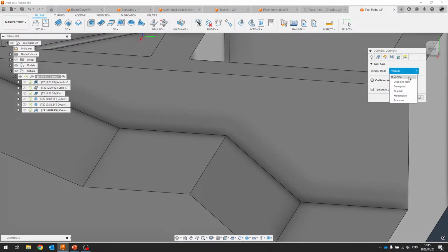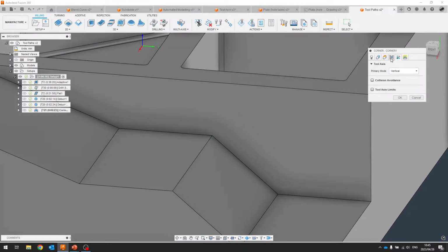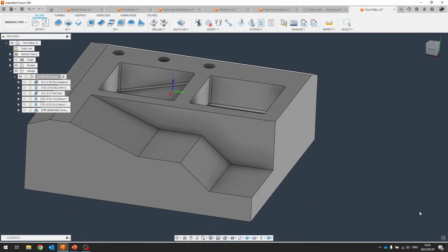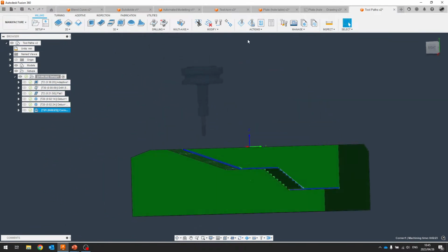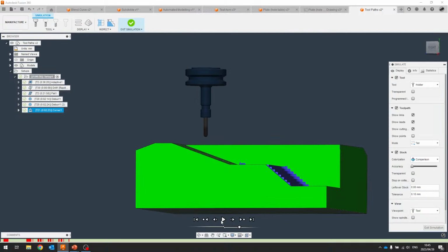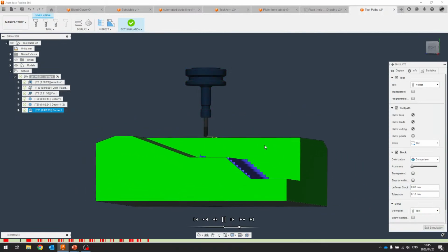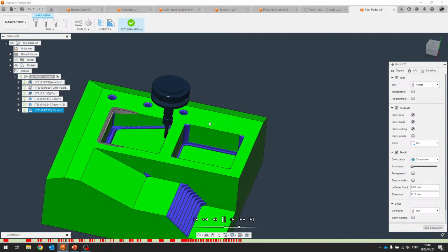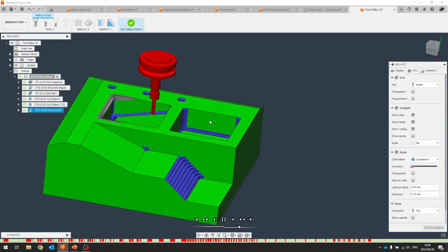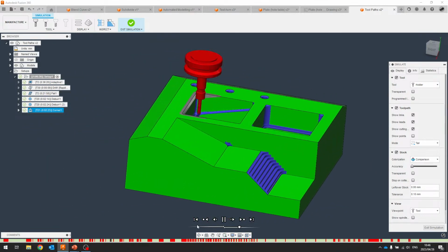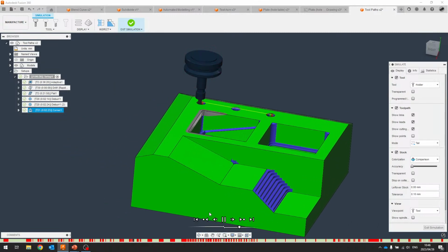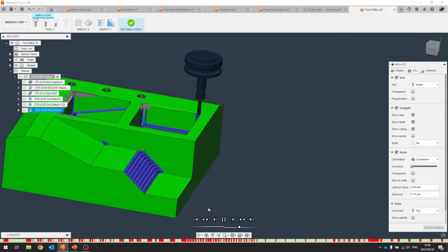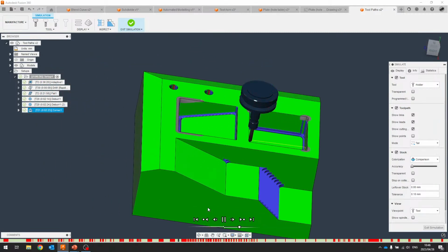So you've got those steep and shallow settings for the corner toolpath, as well as the tool axis modes. The primary mode, you have vertical. You can go through, set up your tool axis as per normal when changing over to using simultaneous machining. And that will then go through and I'll just simulate this. That will go, and we'll see that that uses that 5-axis. Clearly my tool is not set up correctly for doing the machining in the deeper pockets. Getting a lot of collisions there. Probably should have chose a better tool for this, but we can see it following and finishing up those lower and or the steep and shallow corners.